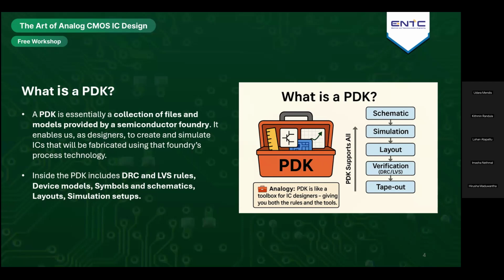Think about it like this. If we were building a house, the PDK would be our entire toolbox. That means complete with hammers, blueprints, measurement guides, safety rules, and even sample building materials. Without that, we are just guessing. The PDK includes DRC and LVS rules, device models, symbols and schematics, layout, and simulation setups. So overall, PDKs form the bridge between design and fabrication. Without them, designing a real-world IC would be almost impossible.